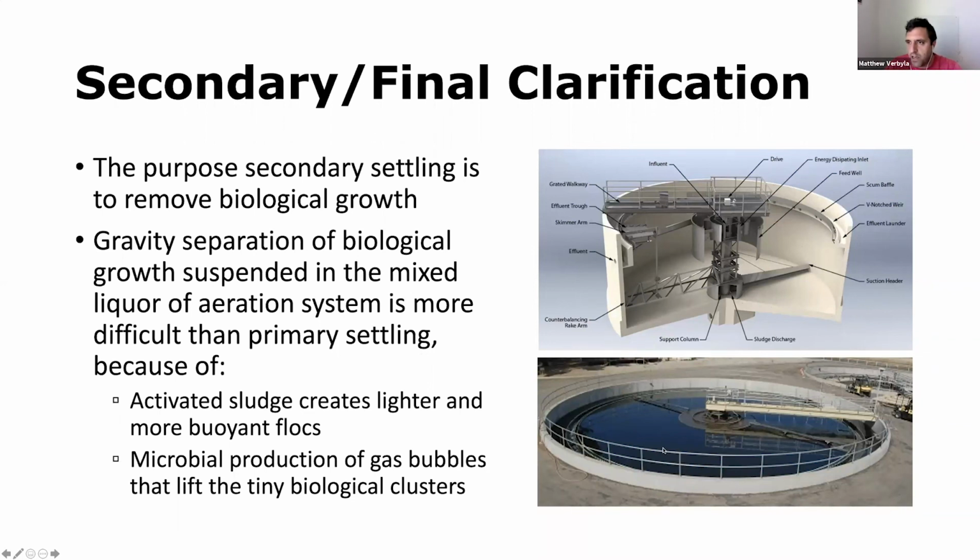And a good operator will know how to manipulate the return sludge rate, or the solids retention time, and the way the system is operated, in order to achieve a good mix of flocs of microbial biomass that produce flocs that are easily settleable in the secondary clarifier.